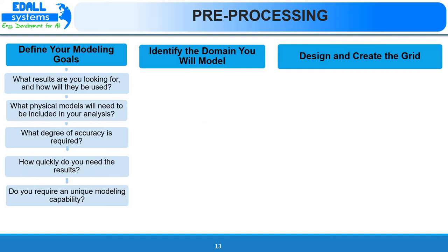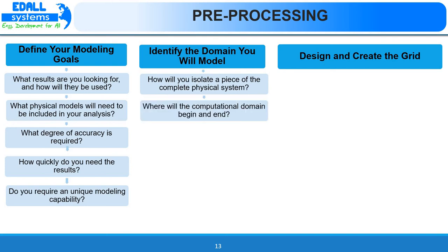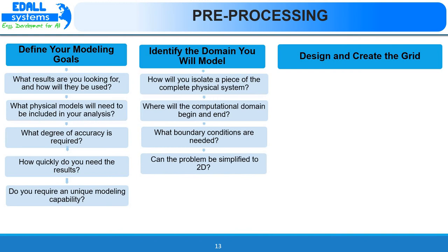Identifying the domain you will model includes how you will isolate complete physical system, where will the computational domain start and end, what boundary conditions are required, can the given problem be simplified to two dimensions.